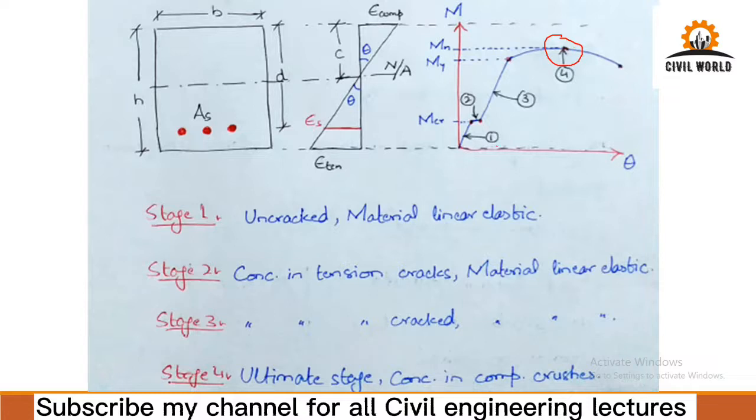So we can basically divide this whole profile into four stages. Stage one, where the concrete has not yet cracked. Then a particular instant when concrete has cracked, and then when all the tensile stresses are taken by the steel, this is stage three. And when maximum moment capacity has been reached, that is basically our aim, to calculate the maximum flexural capacity of the reinforced concrete beam, which is the most important stage, stage four.